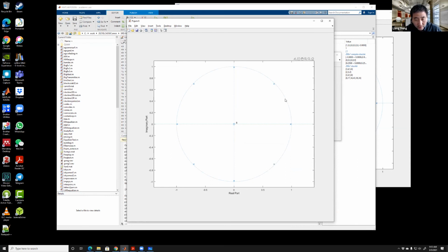I have exactly those 8 poles. Now, when I travel on the unit circle, I'm checking frequency. If I'm moving close to DC, or close to frequency pi over 4, I should get a large number because it's close to a pole. You just simply have this H(z), this number, quite large.